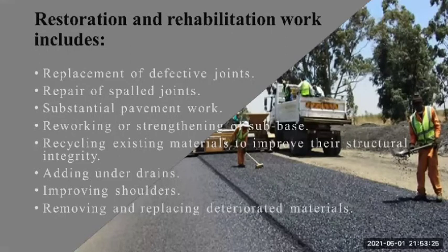Restoration and rehabilitation work includes replacement of defective joints, repair of spalled joints, substantial pavement work, reworking or strengthening of subbase, recycling existing materials to improve their structural integrity, adding underdrains, improving shoulders, and removing and replacing deteriorated materials.